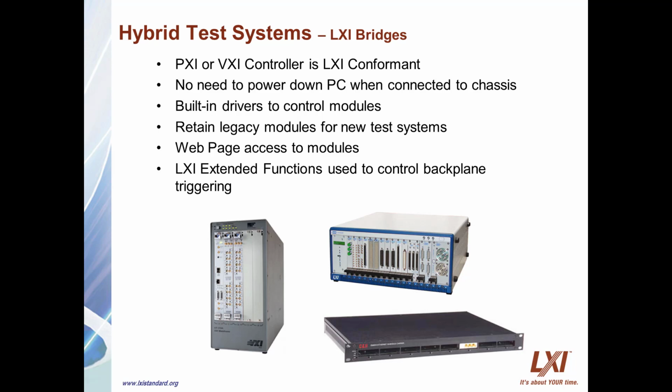Companies such as VTI Instruments and Pickering Interfaces provide LXI bridges that enable the reuse of expensive modules to be deployed to new test systems. The LXI chassis has an embedded controller that requires access to the source code for the various modules that are supported, which are often restricted to the particular company's modules. The same controller gives the user a barrier between those modules and the test system computer that provides all the features of Ethernet connectivity, including web-based management of each of the modules.